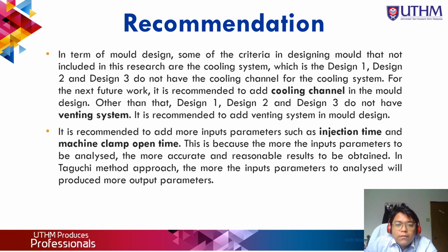So the next one is recommended to add more input parameters such as injection time and machine clear open time. This is because the more input parameters to be analyzed, the more accurate and reasonable result to be obtained. In Taguchi method approach, the more input parameters to analyze will produce more accurate results.